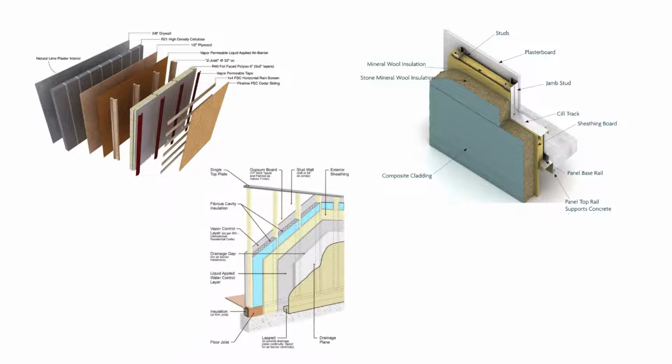Repeating the previous steps will enable you to create any type of multi-layer walls you may need in your project. Follow this workflow and the types of composite walls you will generate are unlimited regardless of the materials used, either as a structure or a finish layer. Notice that you can also include substrate layers and insulation layers to your walls as per the specs of your project.